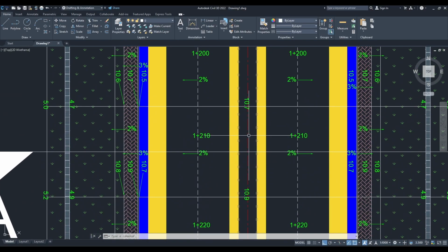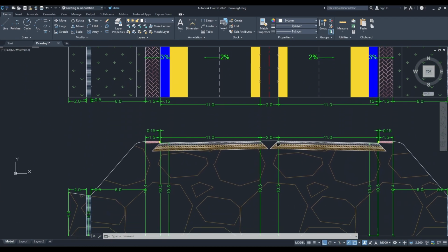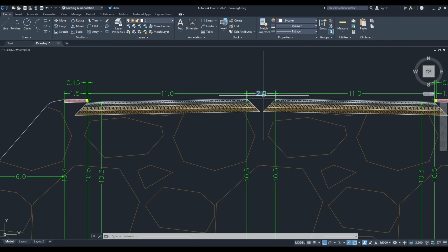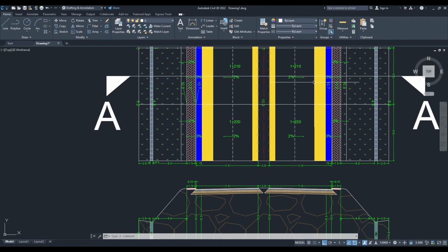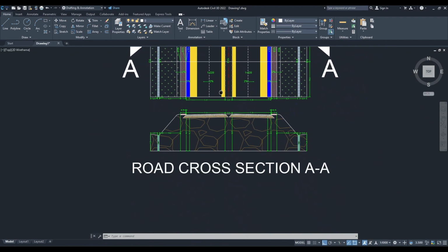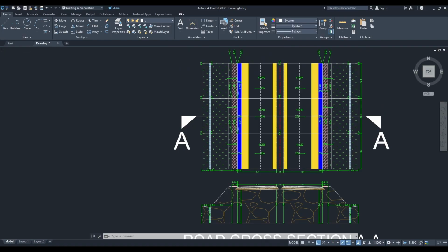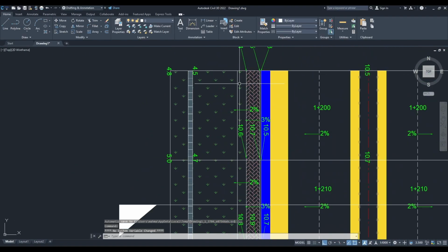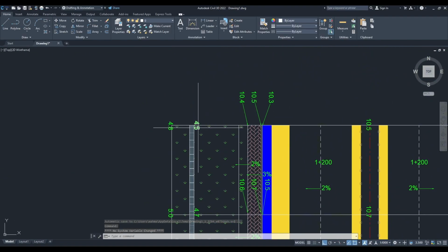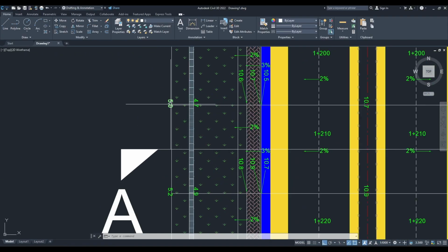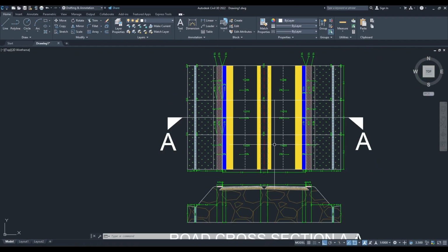So here the median is 10.7, so we would have to change the median and elevate it 0.2 meters from the upward direction. So this line or cross section represents the part of the cross section of the road that is made here, and elevations that were 10.4, 4.5, 4.8 here will be changed to 4.7 and 5 and 10.6.